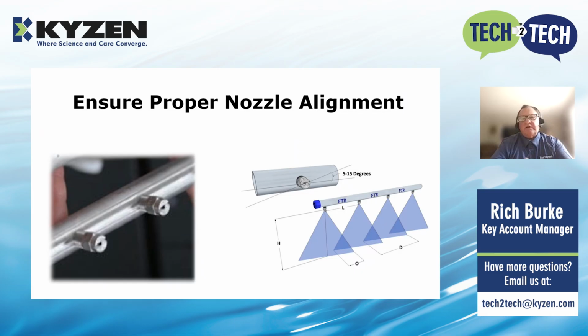And after we've inspected our nozzles and go to reposition them within our manifolds, it's very important to ensure proper alignment of the nozzle within the manifold. Here's an example of fan jet type nozzles, and in these cases, you generally would see fan jet nozzles have an offset anywhere in the 5 to 15 degree range. And the reason for that is we want to make sure that we have full coverage and not interference coverage between nozzles themselves. But the important thing here is to, again, position the nozzles within the manifolds as they're intended from your supplier.